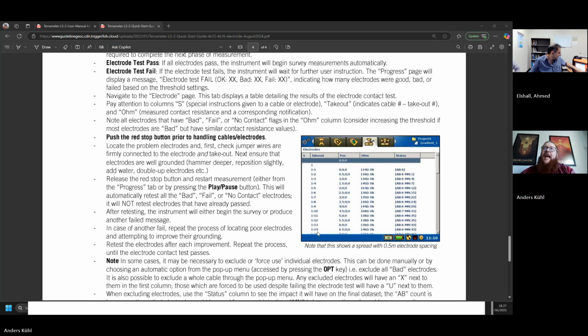The position of every electrode should be incrementing with 1 meter, because we are setting it at 1 meter. If we use the default value, it would be incrementing at 2 meters. So it would be like 2, 4, 6. So that's what it's using to do things. In this image, it's using a half meter spacing. Maybe the first time we use it, we just do the 2 meter. Might be easier, just to get acquainted with it.